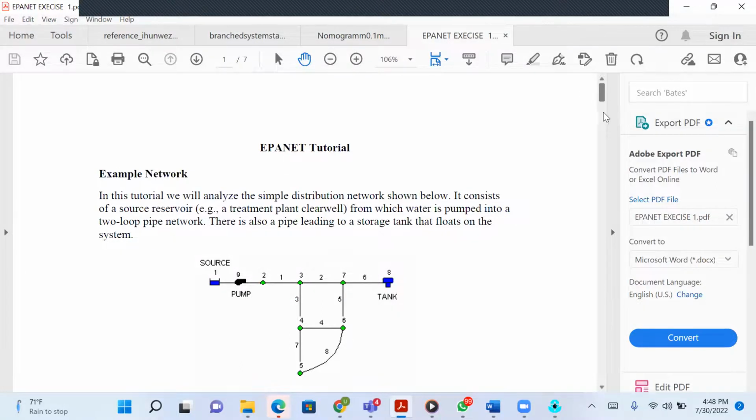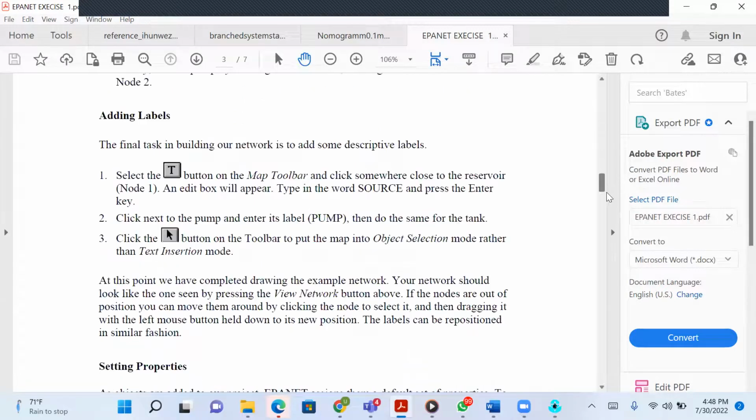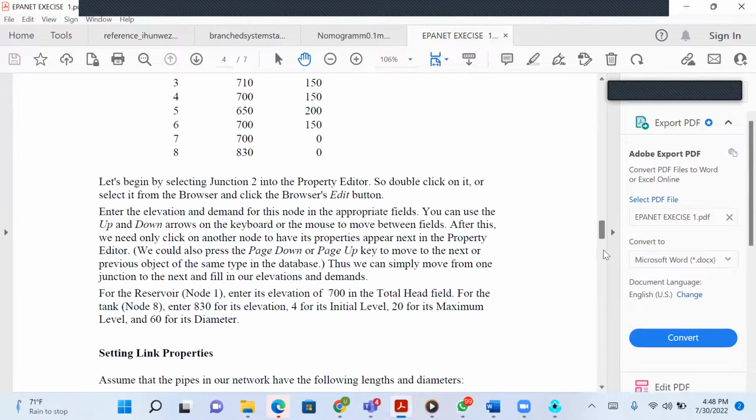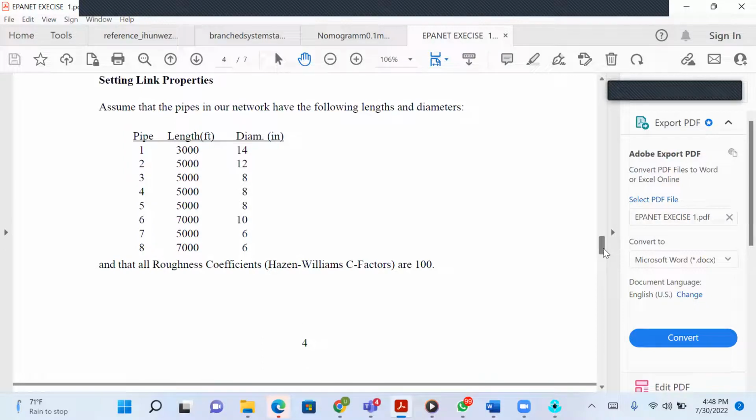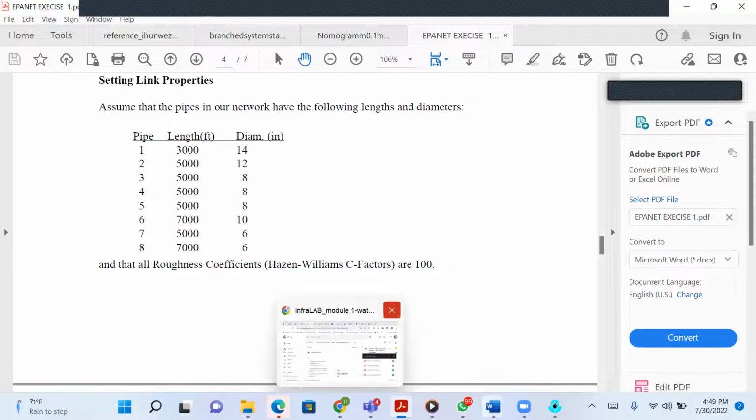Then further, you also have to get the remaining 2 parameters for the pipe. Those are the pipe parameters, right? Which are the length of each pipe and the diameter of each pipe. So each pipe must have a length and it must have a diameter. With those 4, you move to your EPANET software and model your network.